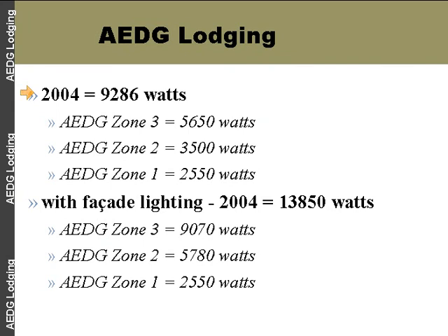It was pretty much just a requirement on lumens per watt, and I could have actually lit that exterior parking lot to maybe 1 watt per square foot. There was no real requirement. So 2004 actually had some specific requirements for walkways and pathways and parking and so on and so forth. So we used those as the base.